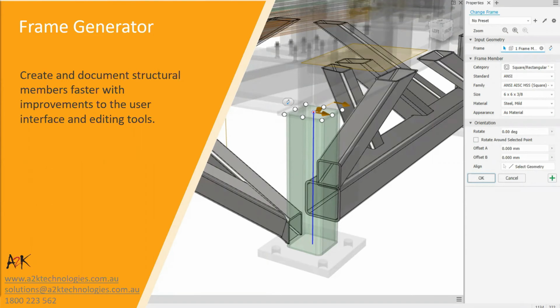When creating your frames, a new category filter enables you to narrow down your selection, and preset configurations now help you to save your most frequently used frame settings for future use. Geometry can now be filtered within the property panel, and a new preview glyph helps you orient your frame as you select your skeleton geometry. There are new zoom tools to help you orient your frame by adjusting your view to look directly at the frame section or to an isometric view of the frame member when you are placing.